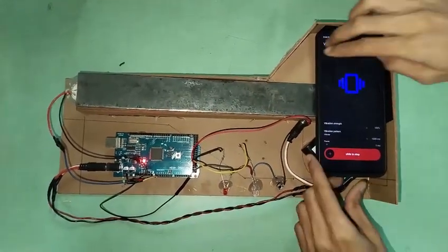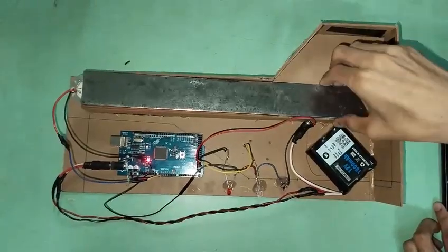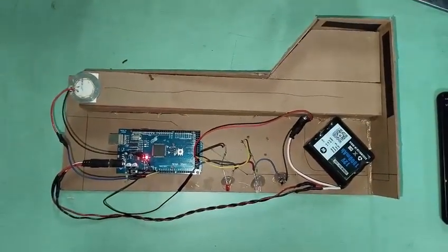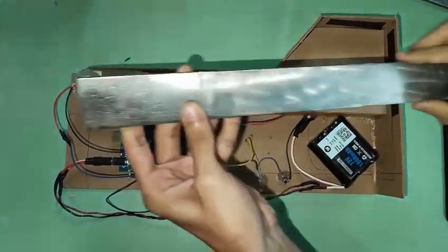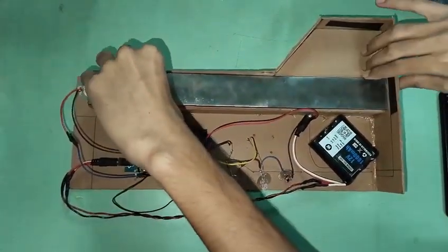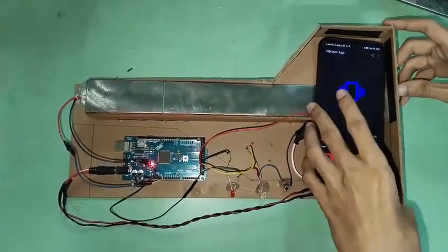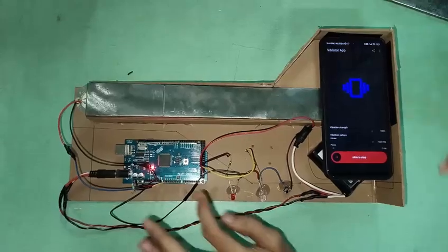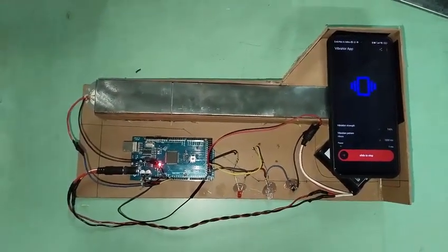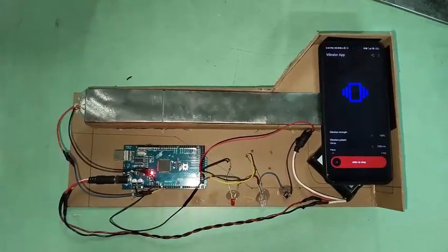So we will put our phone away, change the demo reel unit, and put in the one with the defect. The idea is that this one having the defect will transfer fewer acoustic waves, basically less vibration, which will result in lower readings, and that difference is what we will use to identify the defect. So let's press the button indicating that we have changed the rod, and the light is blinking again, indicating that it's taking the readings.